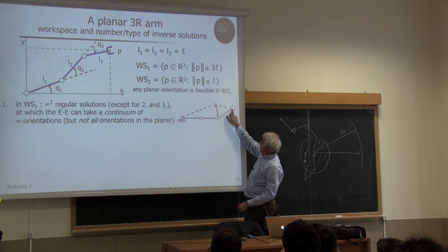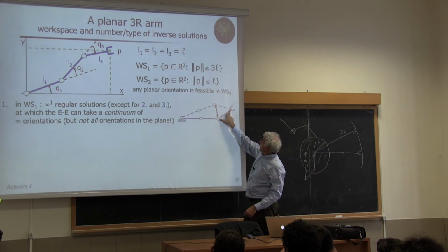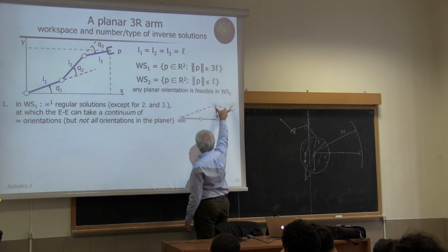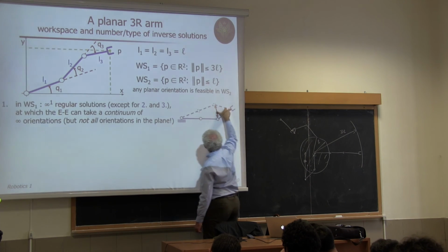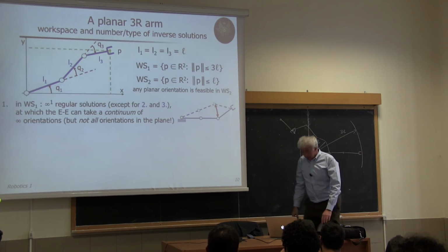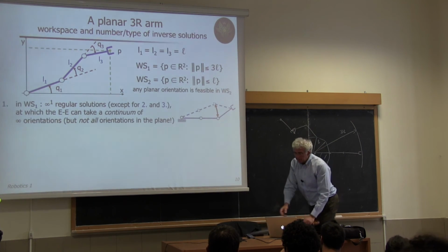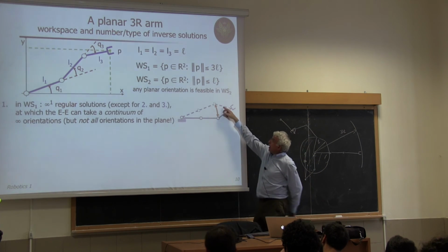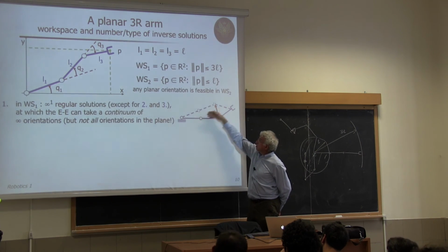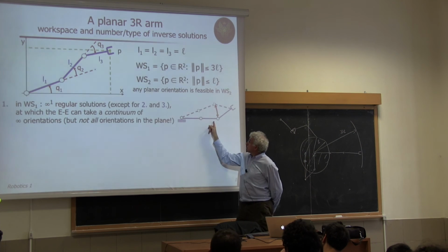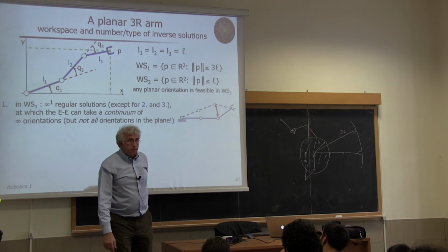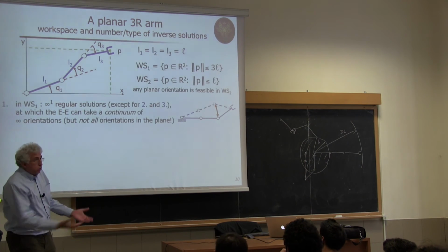And then I place the end effector and I have some orientation. Then I can change the orientation for a while. I cannot assume any orientation because as soon as I go out of this or below this, the first 2 links are not sufficient to reach the base of the third link itself. Okay? So I have all these solutions for the third joint angle, and associated to this I have typically 2, but in this limit condition only 1 solution for the first and second joint. Okay?